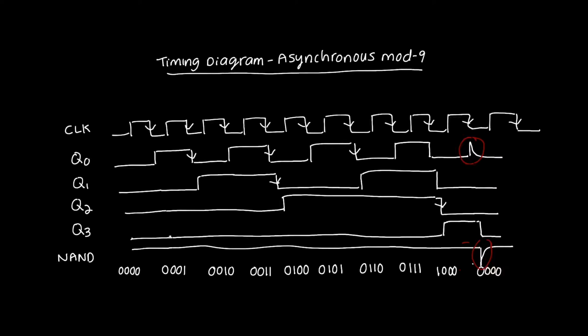So looking at Q2, we see the same thing at the falling edge of Q1, some short time later, given by the propagation delay of the flip-flop. Now, this is a characteristic of the particular flip-flop that you're using and the logic family that you're using. So here we see some short time later, it does not happen instantaneously, Q2 will go high, and we have the same thing over here because Q2 is the clock for the flip-flop whose output is Q3.